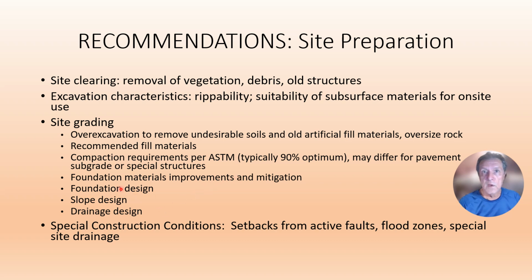You're going to discuss the foundation design. If you're on a hilly site, you're going to address slope design and also design of cut slopes and fill slopes, whether they can be 2-to-1 or 1.5-to-1 or what have you. And it's also important to mention parameters of drainage design. You may have some special construction conditions. You might have to include setbacks from active faults, building setbacks. You may have to talk about flood zone setbacks and site drainage.